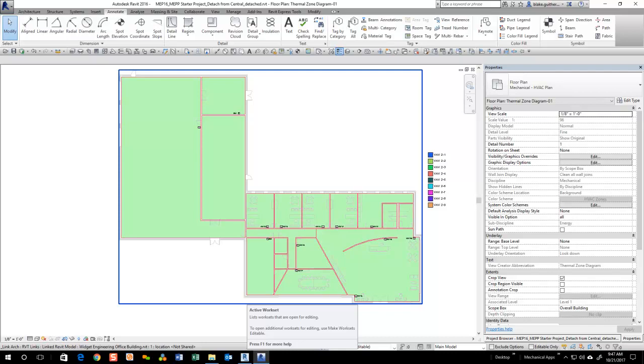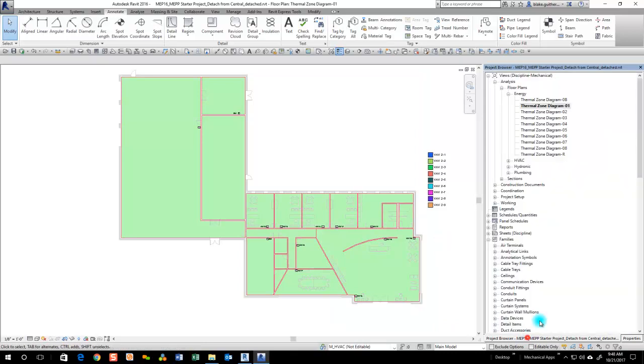It allows you to get the calculated values into the spaces, which allows you to compare actual to calculated airflows at diffusers, which then trickles down into equipment sizes, connected capacities. So this is essentially step one. We've set up some workflows to help you guys get load calculations done faster. And whether you're using third-party load calculation software or if you're doing it in Revit, this process right now doesn't really change. It starts with setting up the thermal zones in Revit.